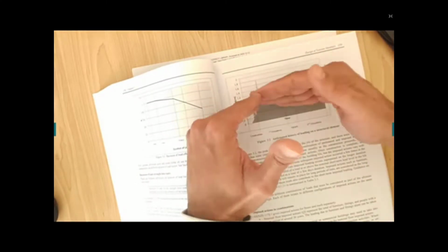Okay, when you construct your members, your loadings are very small. On the first day, you take an occupancy. You will have about 1 to 1.2 to 1.4 kilonewtons of loading. For a significant period, you have vacations, you don't invite a lot of guests, you have some vacant positions. Take an occupancy, let's say you have family, you are getting older, you become grandparents, you have grandkids and all, again some of the occupancies come here. So overall, if you take the average for the whole duration, you might have 50 years of the structure's life. During the 50 years, you might end up with 5 days or some stage where you will reach the ultimate point.